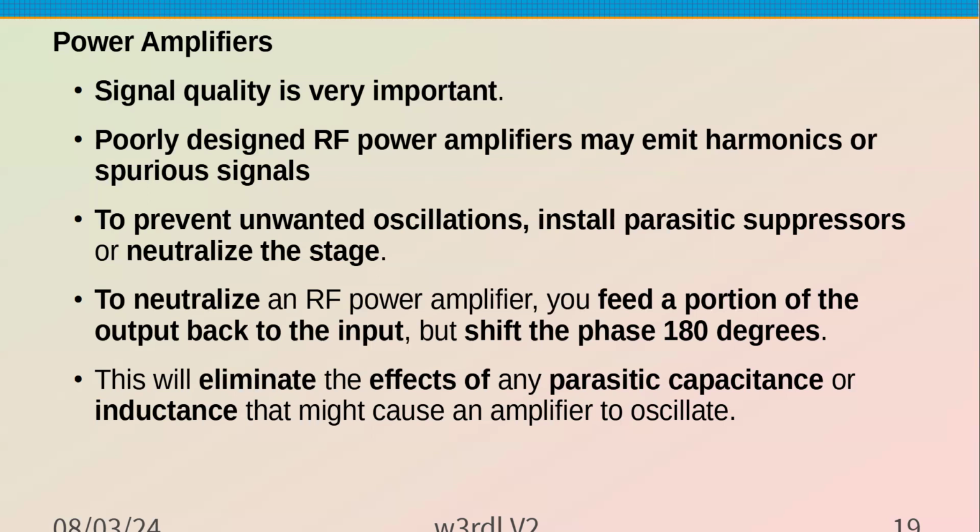So it's actually going to reduce the gain of the stage, but it gets rid of the positive feedback that's causing it to oscillate. That's how you make an oscillator, is you keep positive feedback. The signal is in phase with the input, so it enhances the signal. So neutralizing the stage means that you bring in some negative feedback, with some negative phase shift in it, so it's not in phase anymore, to help neutralize it.